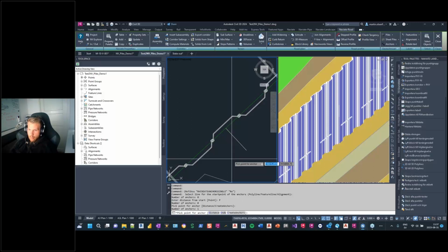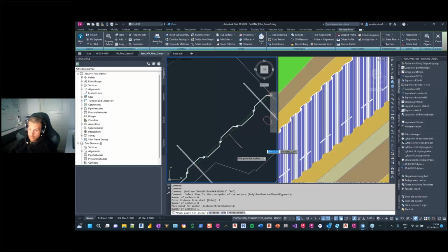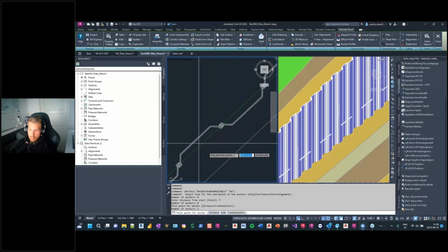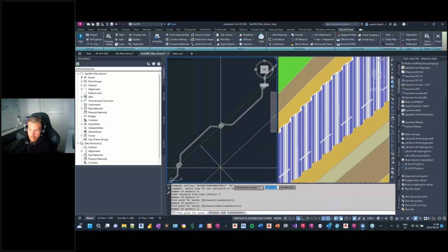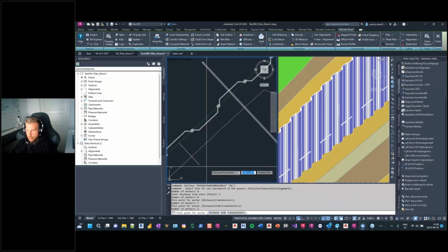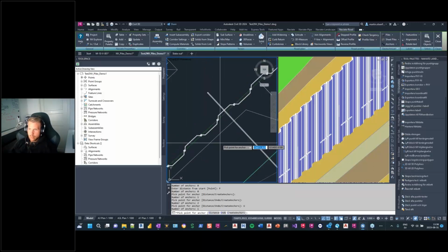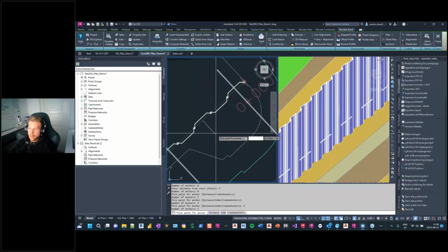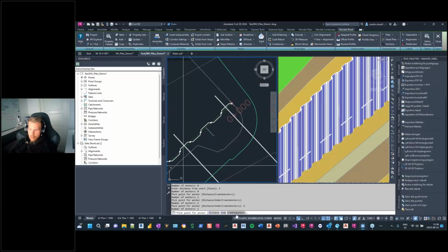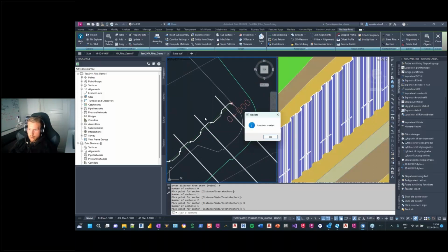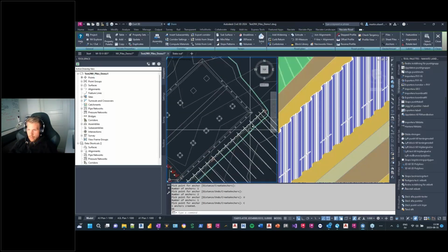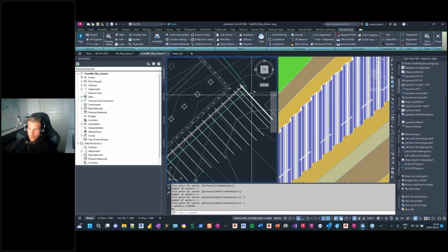I got distance. If I want to put the next one on a distance, I can undo this, or I can just hit create anchors to create that one. But if I create another, just to show, activate midpoint, and then if I'm not happy with that one, I just press undo, and I still got my first one. So when I'm happy, I just choose create anchors, and the anchor will be created. So that's pretty much how anchors work.